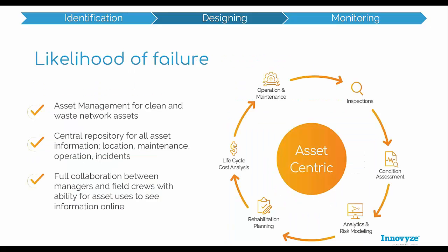And in addition to these tools, and when using a hydraulic model in general for your planning exercises, the asset management tools we have in InfoAsset Planner allow operators and managers to evaluate the structural condition of the network. So looking at the risk and reliability based on the likelihood and consequence of failure. So where might there be potential bursts and leaks in the future? Trying to be as proactive as possible and help you deliver optimized rehabilitation and maintenance plans.